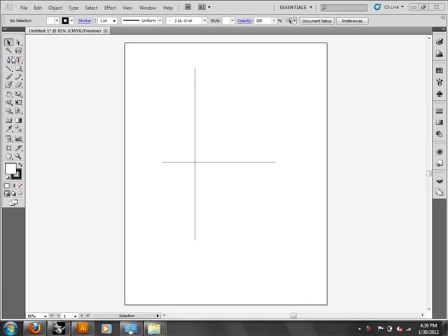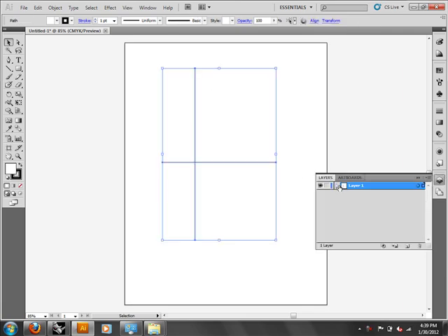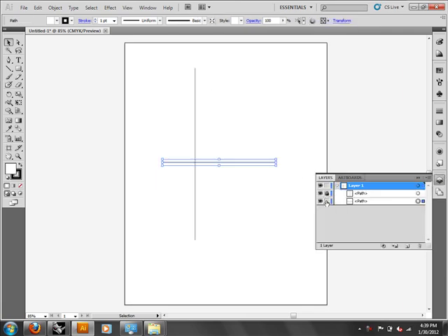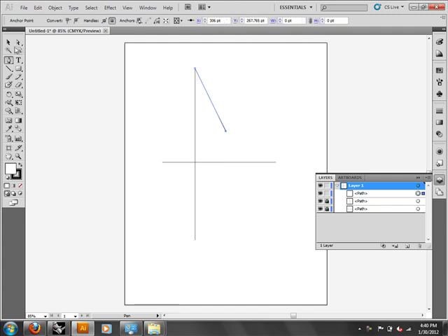Okay, so the point that Thomas was talking about was, let's say you had, I'm going to go ahead and lock these actually. Within a layer, you can lock individual lines as well as the entire layer. So if I wanted to do that without accidentally adding to that line, I think some of you found out that when you use the pen tool on a segment, it tries to add to it. If you don't want that behavior, then just lock that line. So I can snap to that though, and I can draw an angled line.